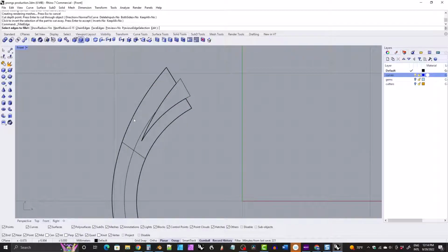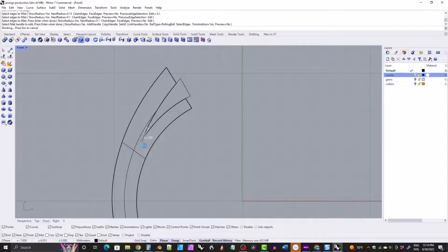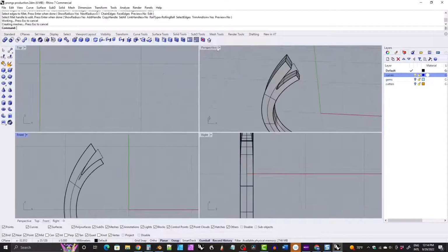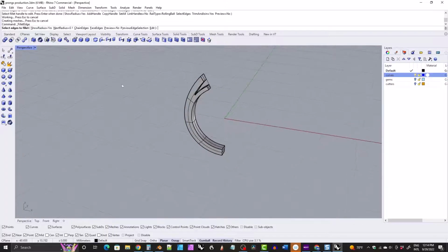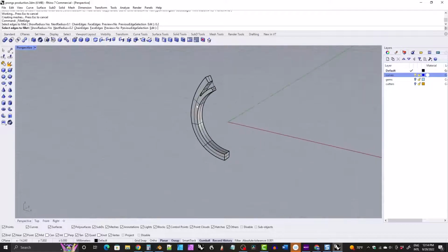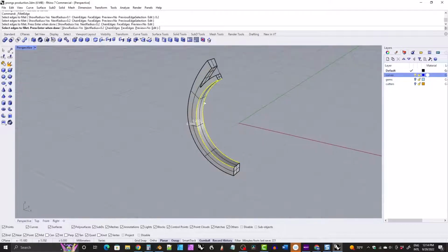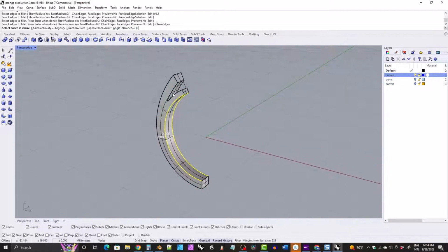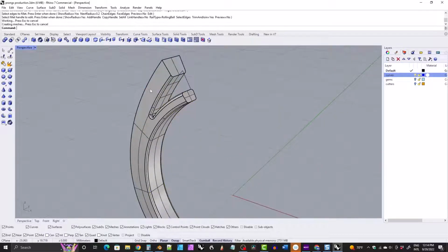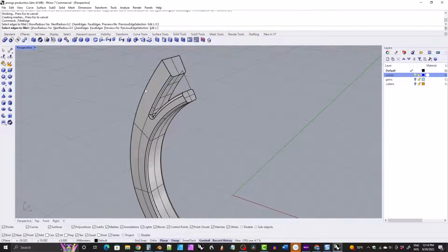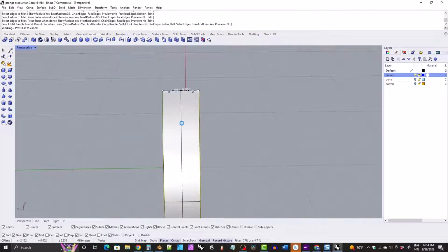And then we will fillet it with a 0.1 fillet, that corner right there. And then we'll fillet everything else just like we did with the other shank. So 0.2, 0.2, chain edges, 0.2, chain edges, 0.2. We'll hit enter a couple times, and then we'll give some 0.5 fillets up here.